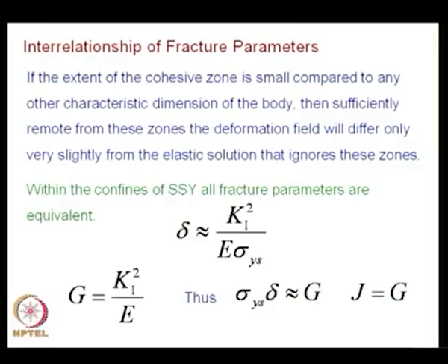So, this gives a sort of a confidence that though the starting point in understanding the fracture behavior is different, they all converge to certain kind of interrelationship. That shows there is certain internal consistency in our understanding of how the crack behaves within the confines of LEFM. The mathematical development in LEFM is much more refined than what you see in EPFM.